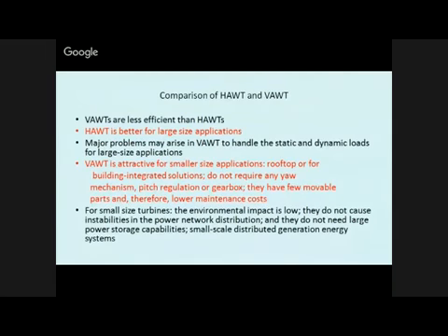They are attractive for smaller size applications, rooftop or building integrated solutions. They do not require any yaw mechanism, meaning you don't have to control them; they are independent of the direction of the wind itself. Pitch regulation or a gearbox is not required. They have few movable parts, which is important from the maintenance point of view, and therefore maintenance cost is low.